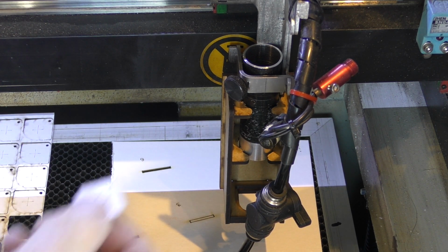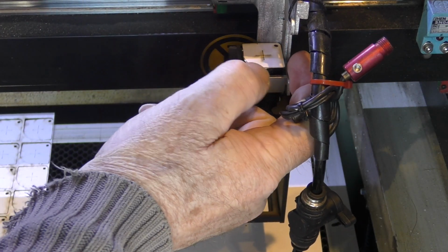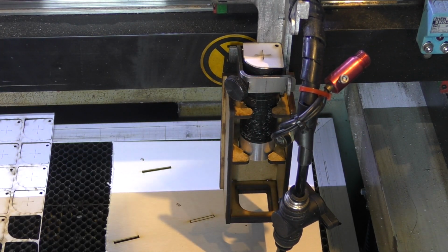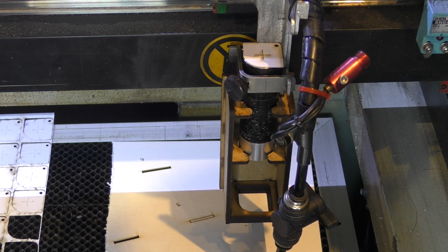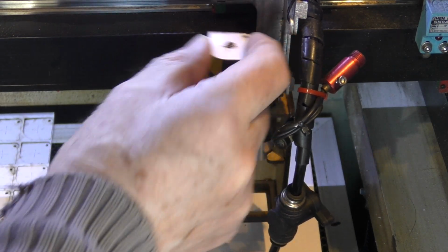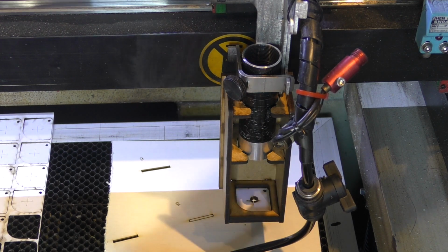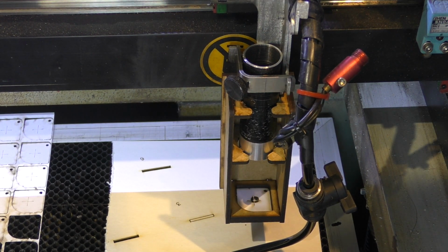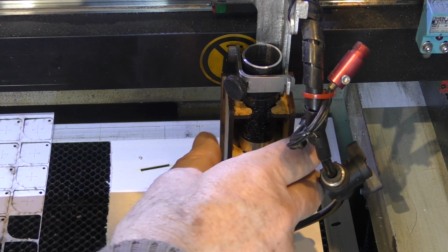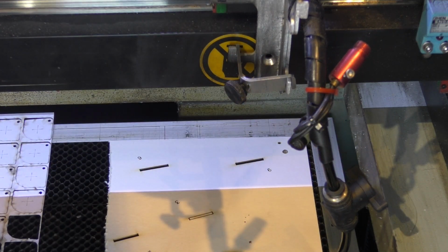Now, the first thing that I'm going to do is to verify that we've got our beam passing right down the axis of the lens tube, i.e. it's passing properly through the axis of the lens. So we'll just do a quick test here, and I think that's reasonably close to centre. We'll now pop it down to the bottom there, and we'll check how concentric the burn is. I think you can probably believe that that is reasonably true, and that we are passing the beam right through the central axis of the lens.